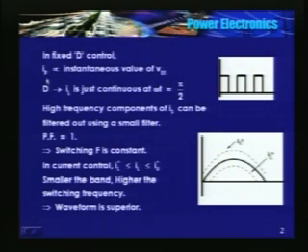But IP, the peak value of the inductor or the source current, is proportional to the instantaneous value of VO1. So we chose the value of D in such a way that the inductor current or source current is just continuous at omega t equal to pi by 2. That's because at omega t equal to pi by 2, when I close the switch for a fixed D, it has attained a maximum value,